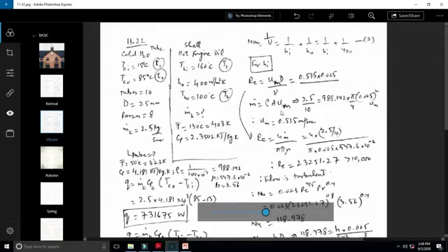So over here we need to use this equation so as to find out the velocity, if you want to use this particular expression, or if you want to skip it and use this expression, you can do this as well. Right, over here what would we be needing? We would be needing the mass flow rate, which has been given as 2.5 kilograms per second, but kindly note that this 2.5 kilograms per second flows through 10 tubes.